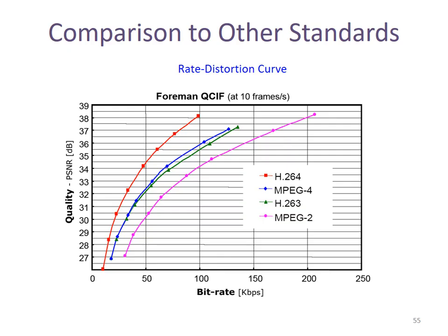Next, let's see how to compare these four standards using this figure. This figure is very famous. We call it the RD curve, rate distortion curve. Rate means bit rate. Distortion means the quality, PSNR. If PSNR is very high, that means no distortion. If PSNR is low, then the distortion is very significant. Next, let's see how to compare these curves to see which standard is better.